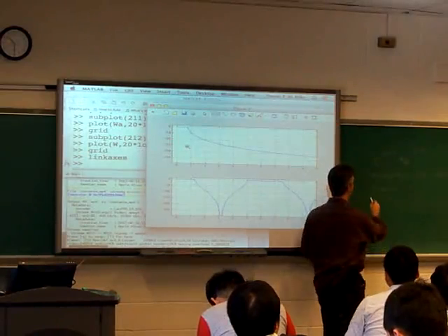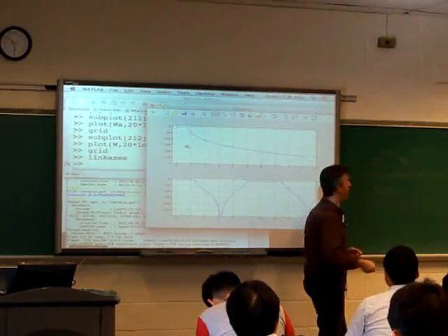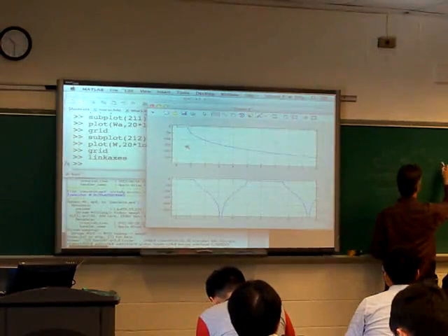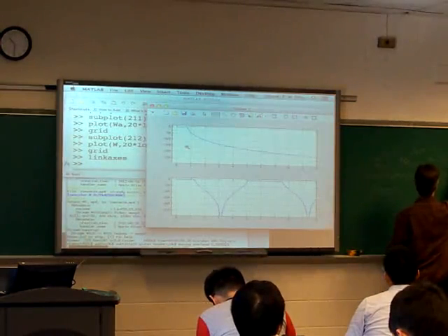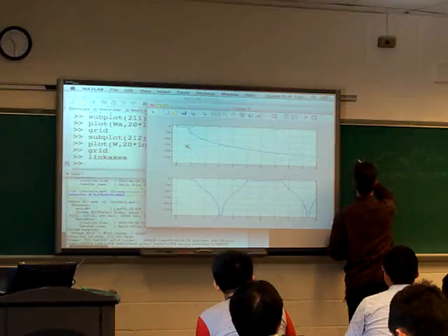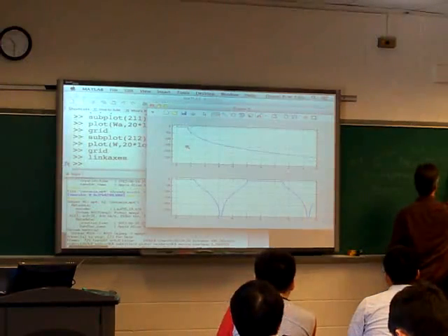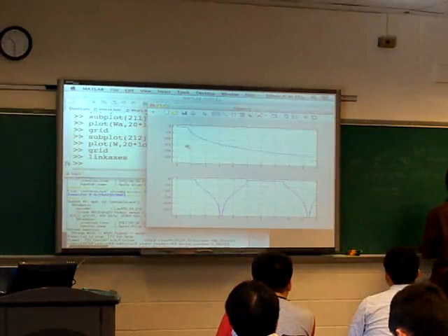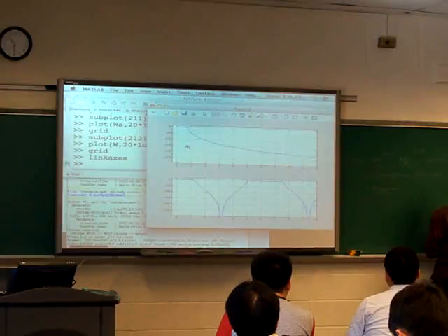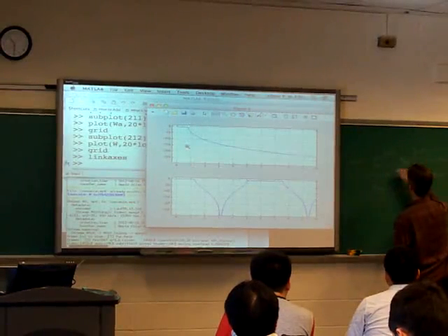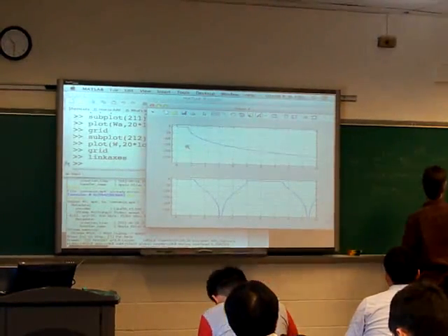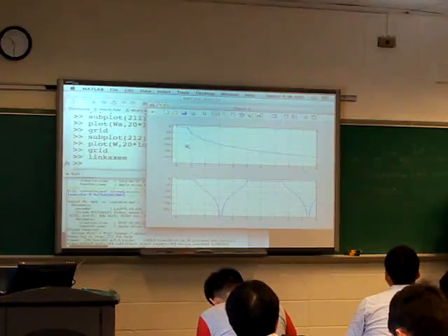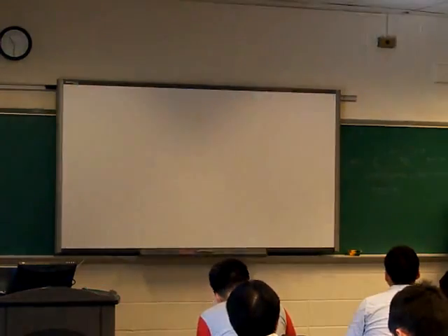So in order to get a real cosine function of time, I need to have these two components, which of course are the Fourier transform of, so if this is x of n, then x of e to the j omega is just going to be delta of, okay, let's call this omega 0 here. It's going to be delta of omega minus omega 0 plus delta of omega plus omega 0, right?